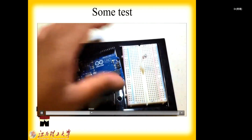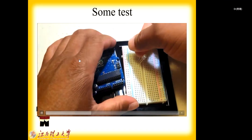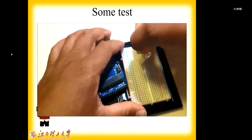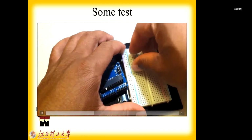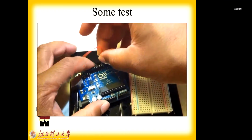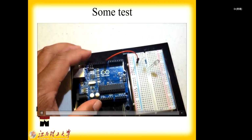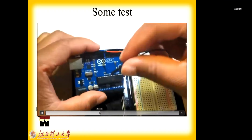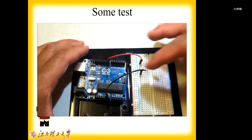You can even put on another LED: take one LED and one resistor and directly connect it to the pin. What should the value of the resistor be? It should be 330 ohms, or 1K to be on the safer side. Simply do it. Connect it to, suppose, pin number 6 or 7, and then the other pin should connect to ground. As you will see, you have ground there. Go and connect, and now run it.